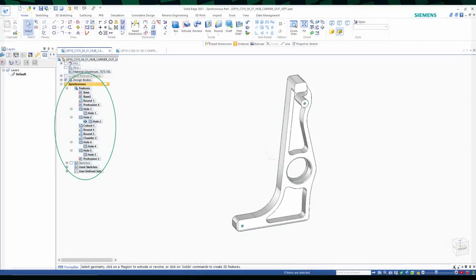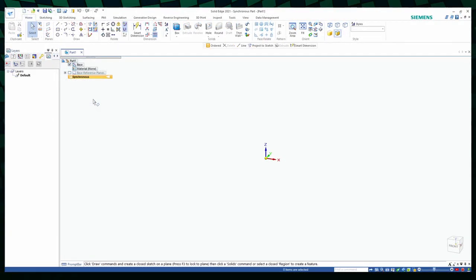On the other hand, you have the synchro, which is feature-based. There is no parent-child relationship, and once you create a feature, you cannot modify it by backtracking to the sketch. Instead, you add features to it to modify the part. Both have their advantages. For simple parts, you can do them quite quickly with synchro mode, but for more complex designs, the history-based tree of the ordered mode might be more useful if you want to change a detail on a certain sketch.